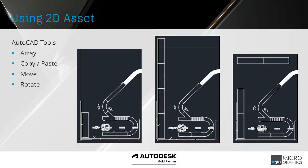So you're able to stick to the standard AutoCAD tool sets that you may already be used to with regards to arraying, copying, pasting, moving these blocks, these asset blocks around within your layout. So essentially you drag the asset in from the browser, it's inserted as a block, and you can work with that block with the standard process that you may already be used to when doing layouts in AutoCAD.